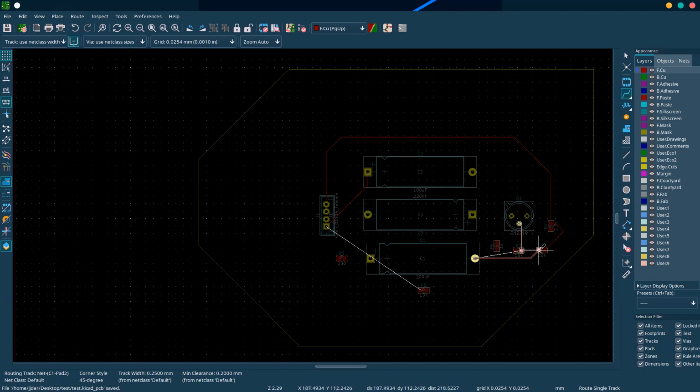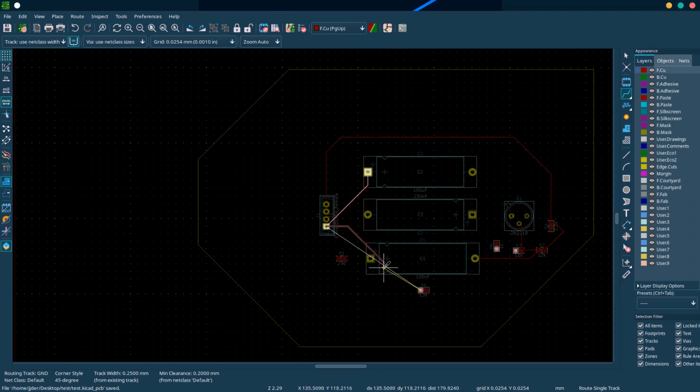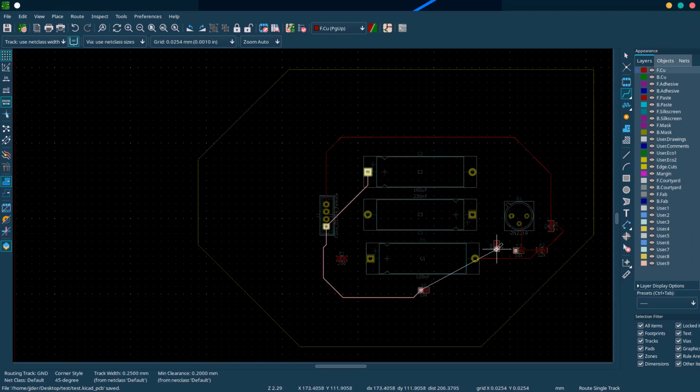On the actual PCBs that we make, we do front, back. How many layers of traces do we do? Try and do two layers if you can, because it gets more expensive to do more. And to be honest, I doubt anything that you do on the team will require 4 layers unless it's a really, really small PCB with a lot of stuff on it. But you do a lot with 2 layers. Just put it that way.